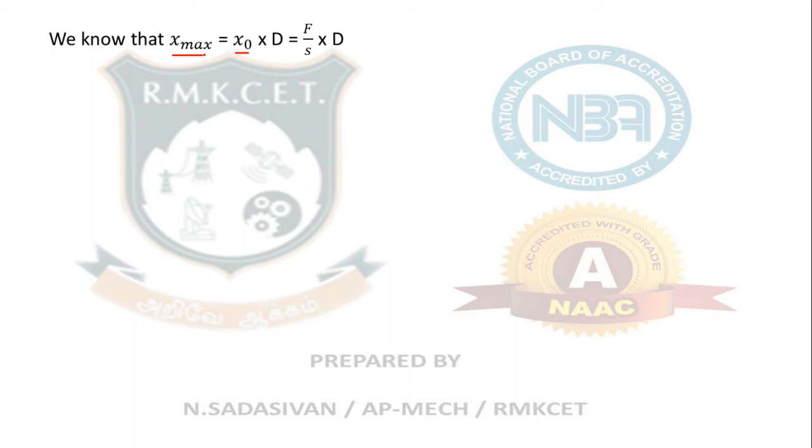Now, what is the ratio between the dynamically created deflection and the static deflection? 4 by 2, which is 2. The 2 is this dynamic magnification factor. Okay. Now, if we multiply the 2 to this initial deflection, del or x naught value, I will get this x max. So static deflection multiplied by the dynamic magnification factor, or dynamic magnifier, will give me the value of x max, the maximum amplitude. So x max is nothing but x naught, which is force applied divided by the stiffness of the frame or the spring, multiplied by the dynamic magnifier. Okay.